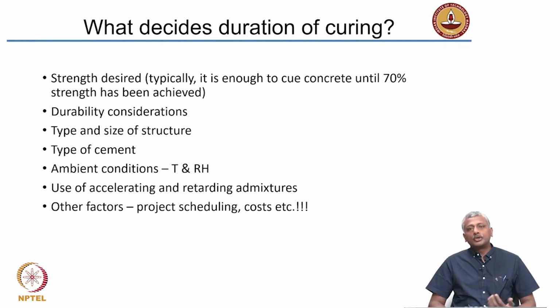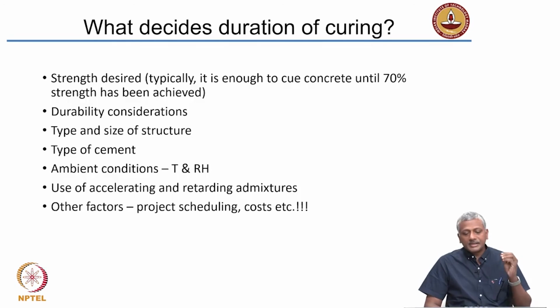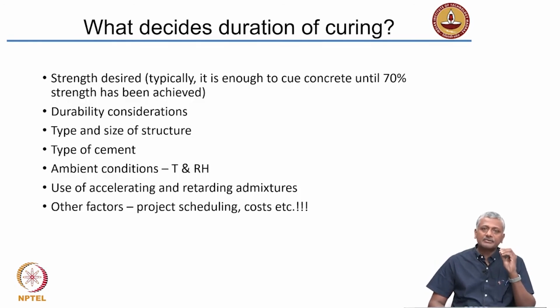Now, how long do you cure? That depends on what you really require. One is, of course, you need to have a certain strength level maintained in the concrete. So typically it is enough to cure concrete until 70% of the design strength has been obtained.